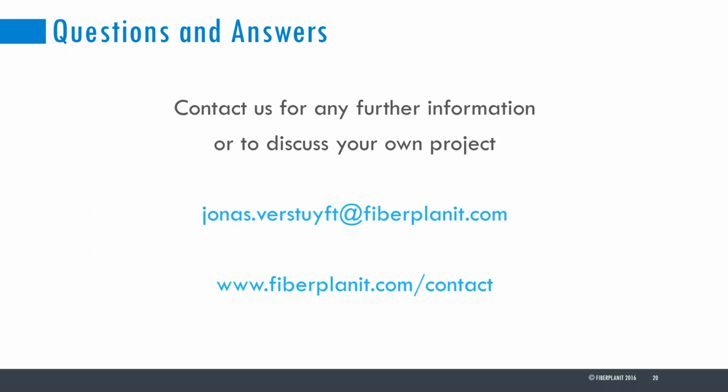So if you have that information available, you can easily load it into the software and exclude it completely from the design, or give a higher cost to these routes. So maybe it's still possible to use these private routes or routes which are difficult to dig, but by giving a higher cost, you can let the software decide whether to use it or not. And you will have an indication of this in the bill of material and in your design output.